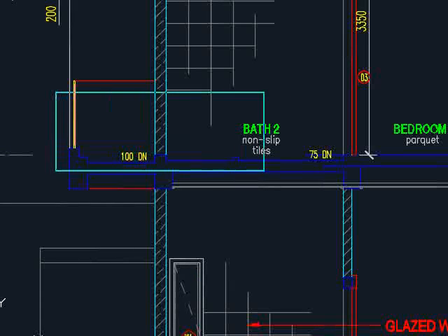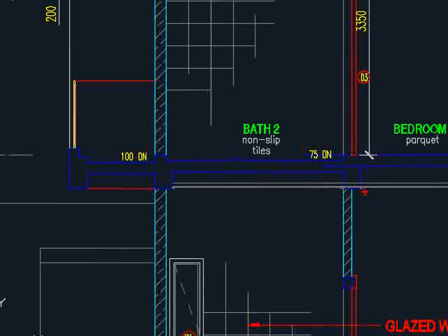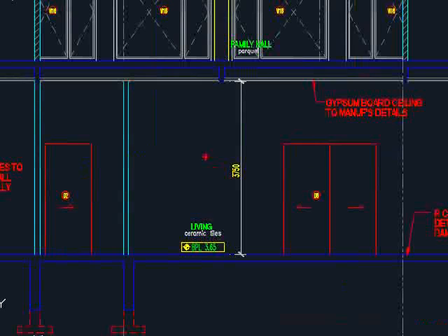You will also see the drops of the slabs, which in this case is referring to the bathroom. There is a 75 mm drop from the bedroom, and you see there is a 50 mm curb, which you can notice from the floor plan given, and the balcony here. There is information given on the headroom, which through plus and minus you will know the space allocated here.